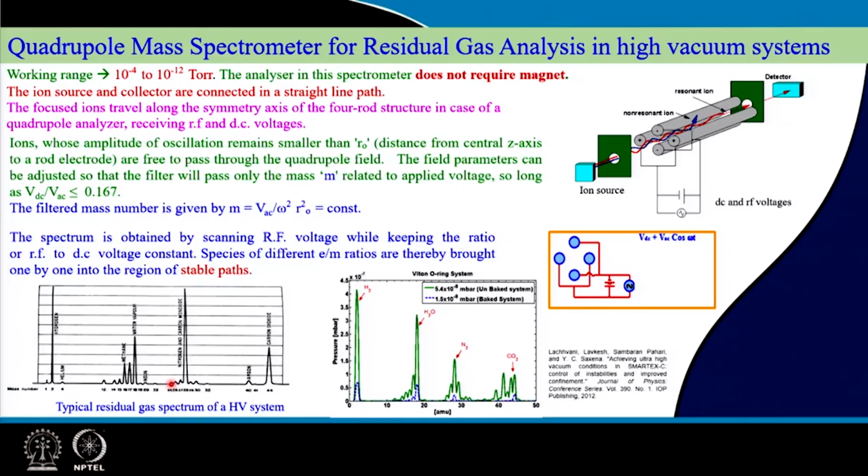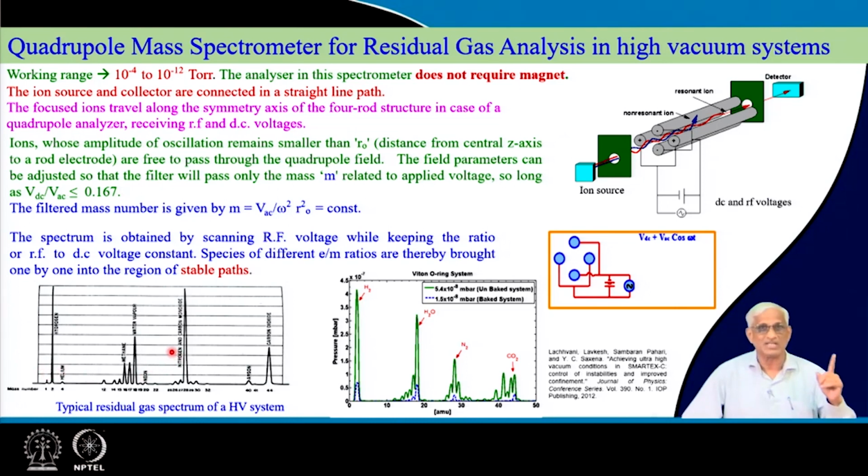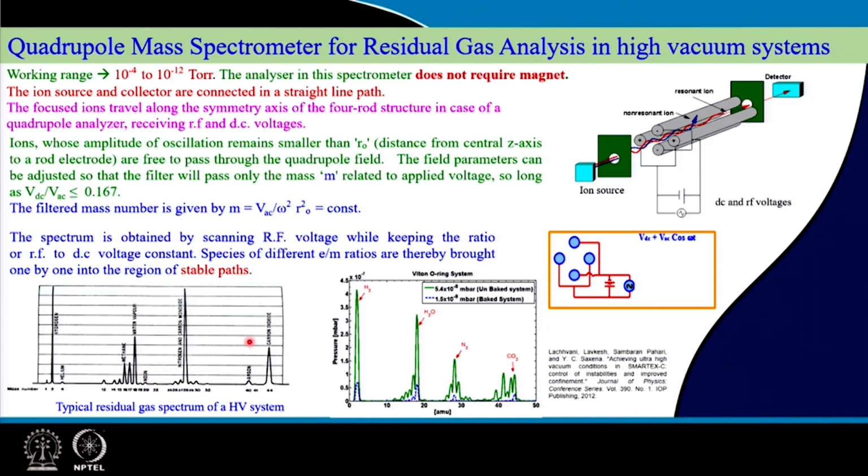Now, coming to the picture here, there is a typical residual gas spectrum. When you are coating a semiconductor, under these conditions I have coated, you can tell. Tomorrow, if the reliability of the device is not coming, then you do not know how to interpret. It is like the black box of an aeroplane when an accident takes place. So, from the RGA you can understand that on that day the peaks of silane were not much, hydrocarbons are there and interfering, p type is more, n type is more. That way RGA will be very useful for you.